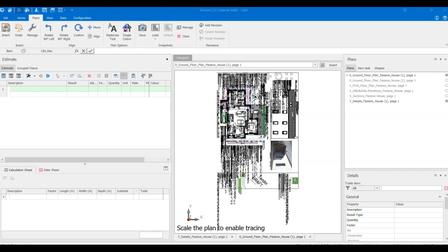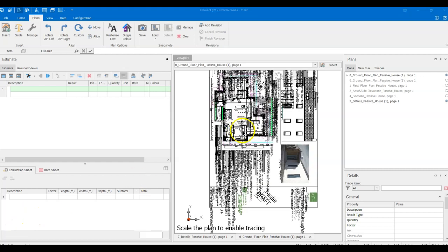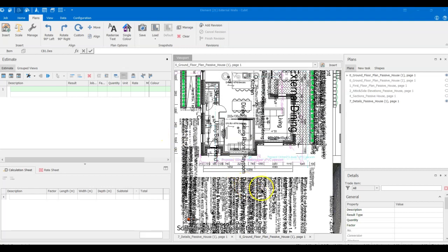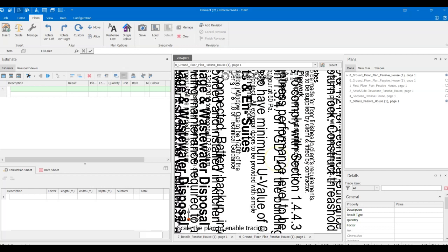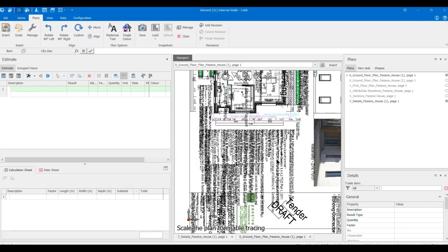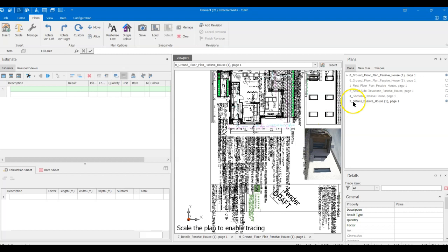I wanted to show you this mistake because I'm constantly making it with these drawings. The default section, I'm used to the default section being vector. In most cases, vector is actually okay, but in some cases, it's not. If you're in a hurry and you load up drawings and you see all this text on top of each other and very difficult to read, don't panic. Chances are you've just clicked the box and imported it very quickly. So you have to manually select raster every time. Just remember to do that.